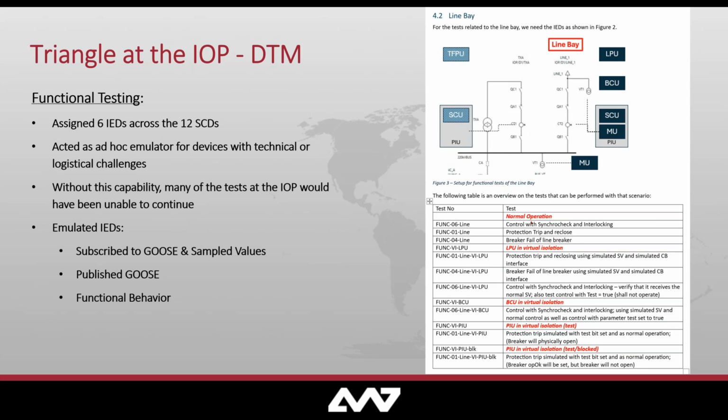Down here at the bottom of the diagram, you see a long list of tests. It can look intimidating at first. Really what we're looking at is just 3 tests, these top 3 up here, and then we repeat those tests in different situations, effectively with different devices in virtual isolation. So with the LPHD sim flag set, so that device could respond to simulated messages from a test set, or even with the mode set to test or test blocked listed in these tests down here at the bottom.